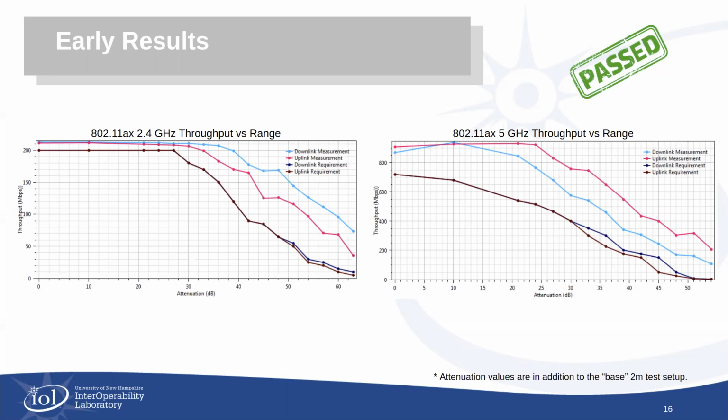One of the other things that's interesting to pull out from these first set of requirements here, if we look over on the right-hand side at the 802.11ax on the 5 gigahertz band, we can actually see that some of those throughputs are pushing well above 900 megabits or so, actually getting close to 940, 950 megabits per second. And that is the TCP throughput there, as specified by the TR398 measurement. Well, you're actually starting to push close to that theoretical maximum throughput at that level, the layer 4 there, of the 1 gigabit Ethernet connection that's coming in and out of that duct.